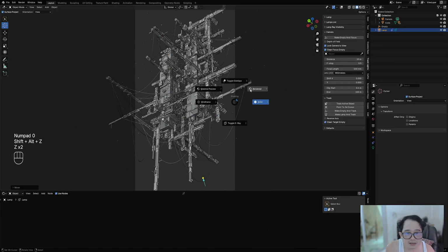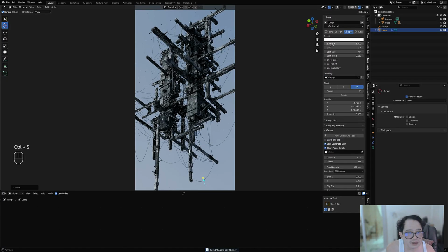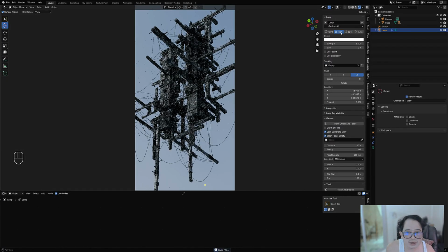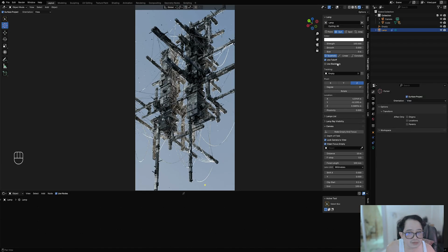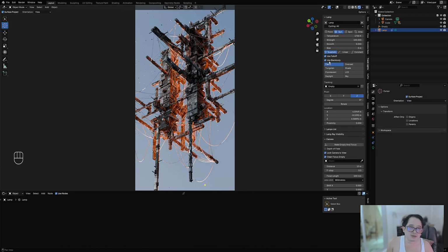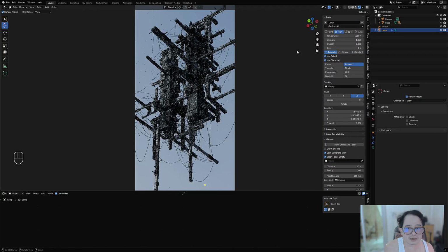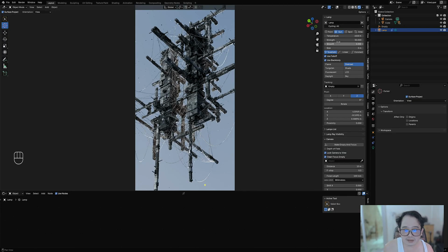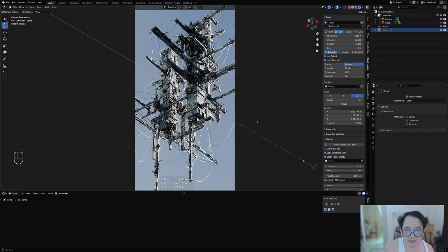And then with the lamp selected, you can change it, we're going to use sun and use full up and black body. If you're using black body, you have a choice of Kelvin presets here. And let's change the strength to something like 50. And then we can rotate it by intervals of 5 degrees. You can change the interval here, or let's just use 2 and then rotate. This is a modal operation.